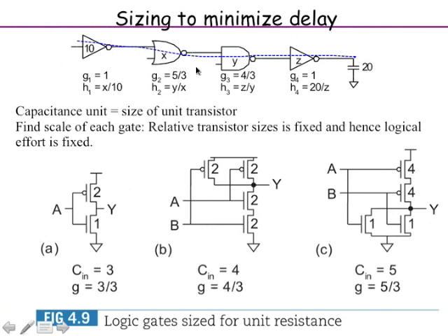So now you can ask the question, why is there this notion of optimum sizing also? If you look at any particular gate, the size X here refers to the total input capacitance seen in the gate. If I call this the unit NOT 2 gate, the input capacitance is 5, whereas this is X, some number other than 5 perhaps.